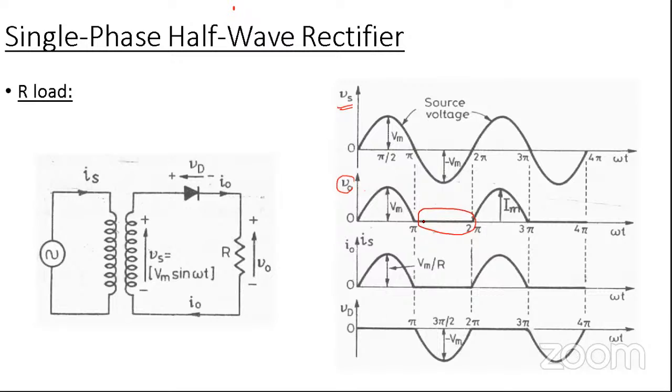And again when the positive half comes, then again you get output voltage. From this diagram you can easily say, without seeing the proper circuit, that this scheme is basically the half wave rectification scheme. Rectification means alternating current is converted to direct current. Okay, so this is the waveform of the half wave rectification output voltage.